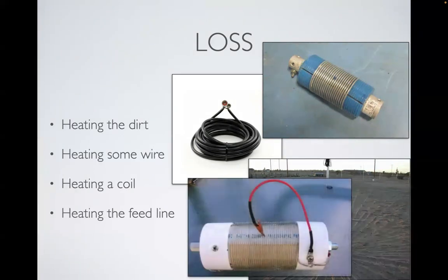But this is the way you don't minimize it. And you may have seen this on some QRP antennas where they have a little shorting wire on the coil. And so you use this to kind of tune the antenna by changing that inductance. And you can think of that as sort of lengthening or shortening the antenna electrically. But does anybody know what the problem with this is?